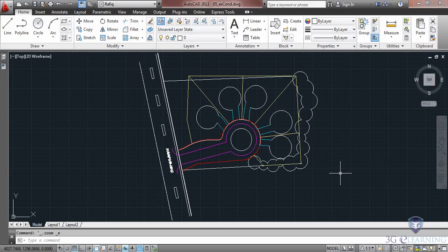When creating external references, we can even link to drawings that are significantly larger than our project area. After connecting, AutoCAD makes it easy to clip large reference files down to size. In this lesson, we will explore how to clip a reference drawing.